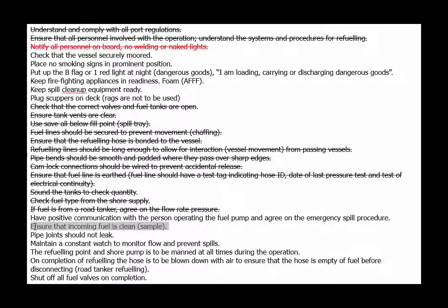We need to sample the fuel. Look, it depends. Normally with our high grade diesel fuel, it's not so much of an issue, but it is a good idea to take a sample and retain it on board. We just get a clean sample container and take a sample of the fuel that's coming in, and if there's any argument or contamination, we've got something that can be analysed. Pipe joints should not leak, that's true. Maintain a constant watch, that's true.